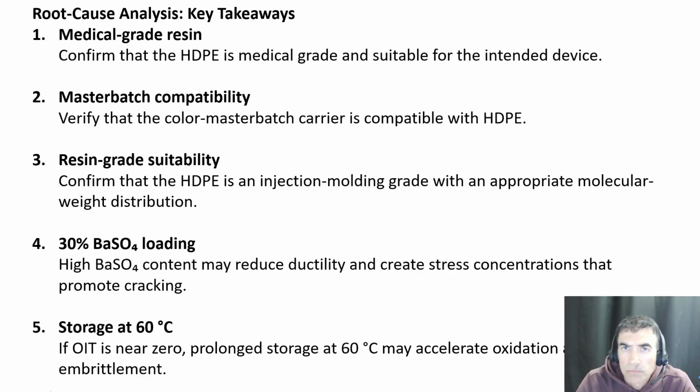Key takeaways from this root cause analysis: first, we found that the HDPE resin or polymer was not a medical grade. When we are working in the biomedical device industry, it's important to start with medical grade polymers. There are more controls over these materials versus non-medical grade.